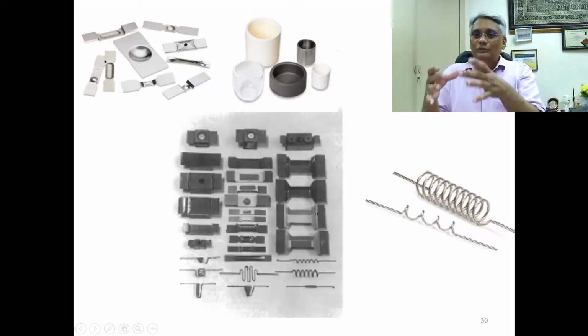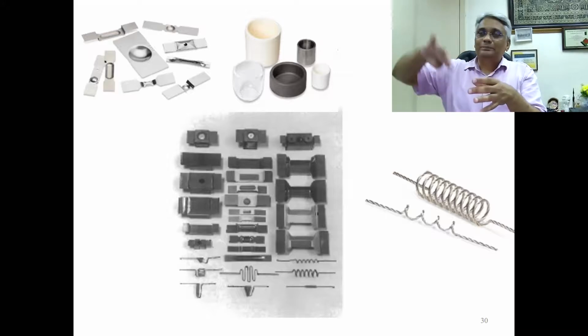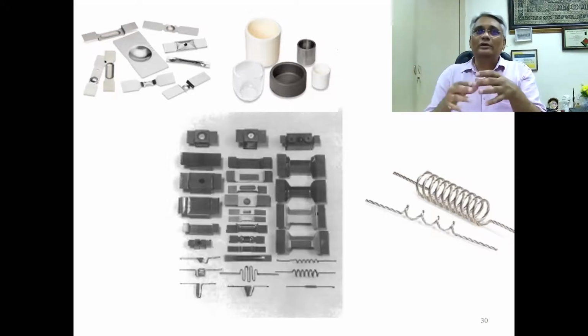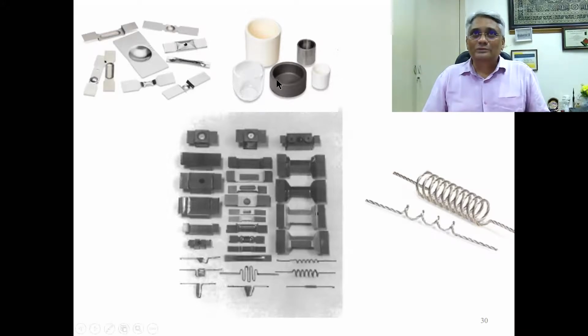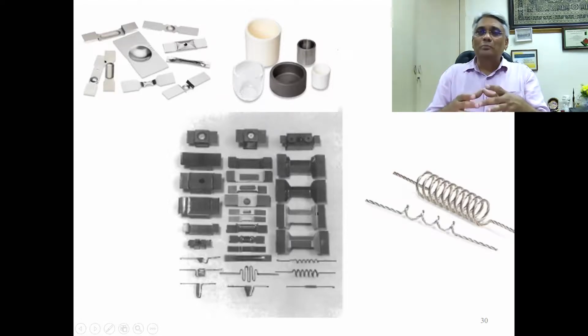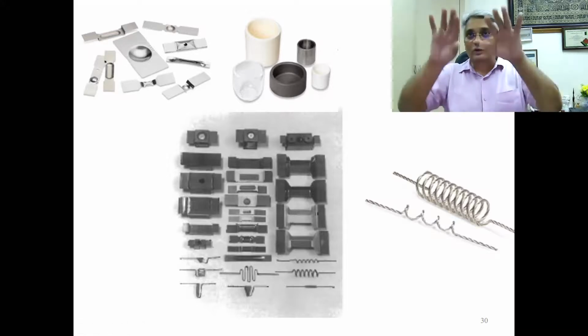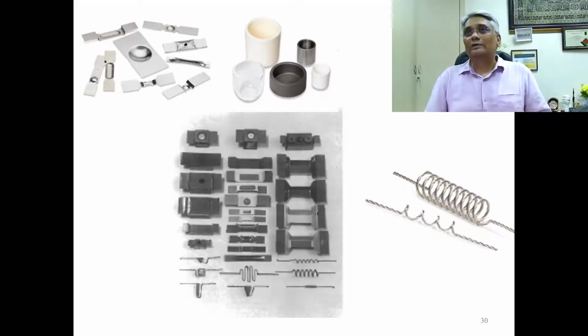In fact, you always see a thin coating of the material that was melted in the previous run. So if you want to use the same boat, or crucible, you can use it for the same element or alloy in the next run, or you need to have a fresh boat because it already has a coating at the bottom.